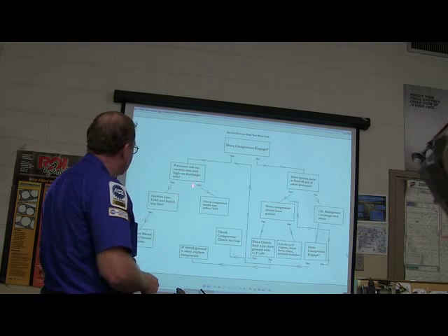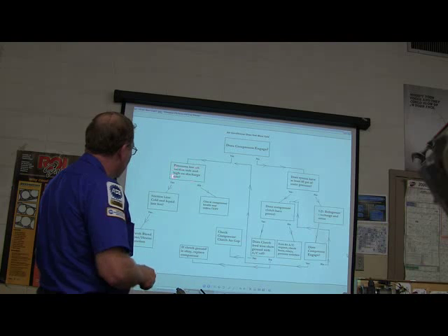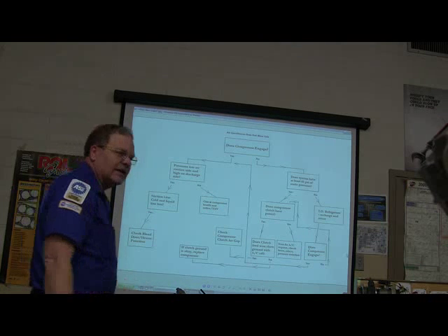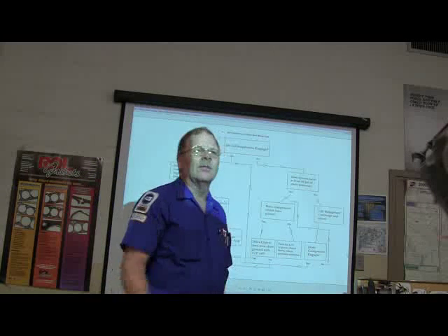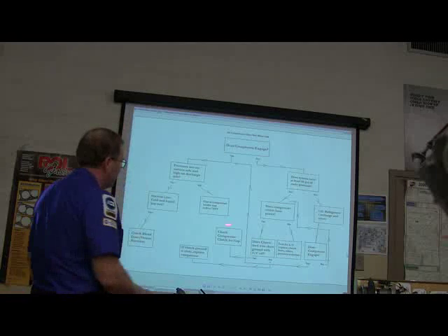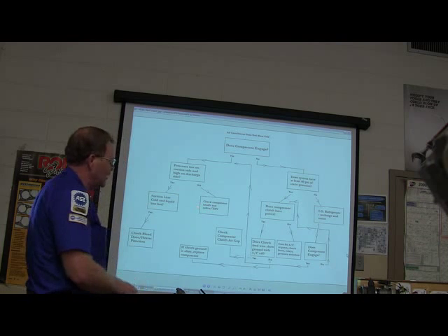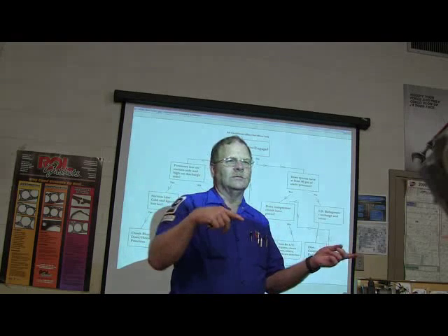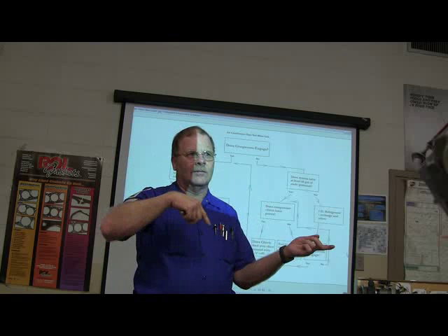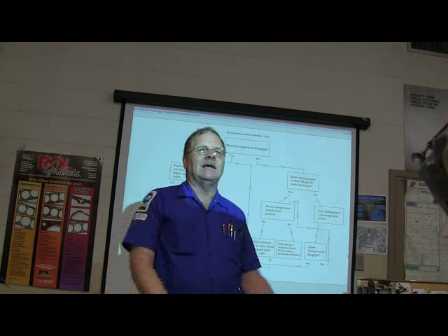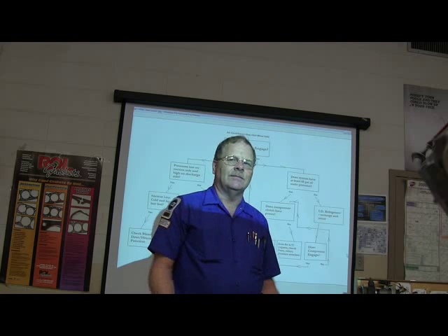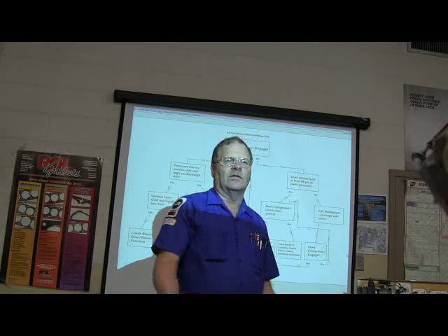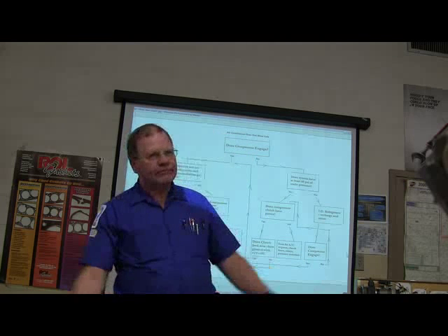All right, so right here, if the pressures are not right, you're going to check the compressor health and the orifice or the TXV. What's TXV stand for? Thermal expansion valve. If the expansion valve or the orifice is screwed up, like for instance, let's say that both of my pressures are really low. That can be as a result of the expansion valve or the orifice clogged up. You know what I mean?